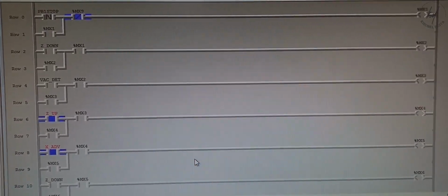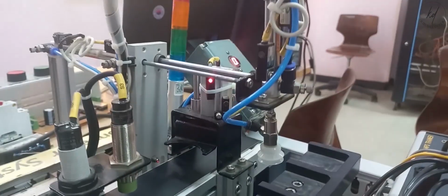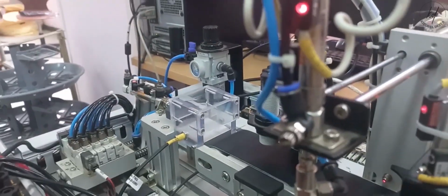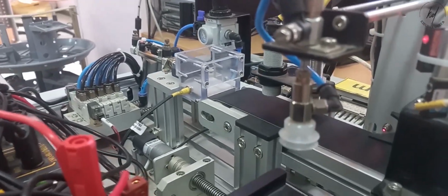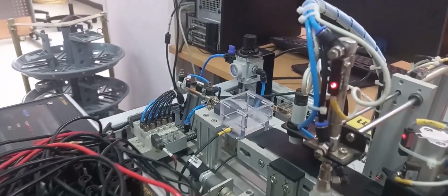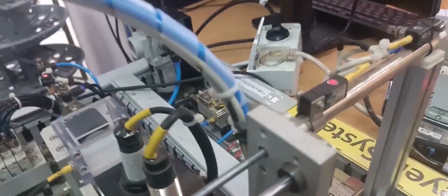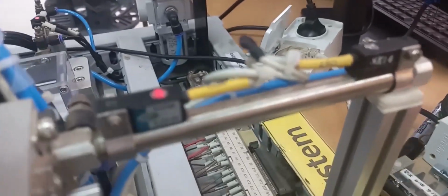Pick and place systems are widely used in automation industries to transfer products from one location to another. It is based on a pneumatic system powered by compressed air or inert gas. A pneumatic system can be controlled manually or by automated solenoid valves. The entire process of gripping and lifting the objects is controlled by a PLC, which is programmed by ladder logic.